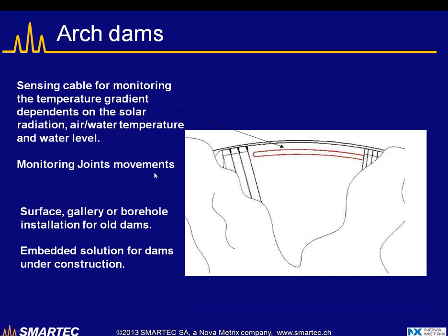Very similar approach for arch dams. In this case, one of the most interesting aspects is the monitoring of joints, and distributed strain sensing cable can be installed in inspection galleries or on the surface.